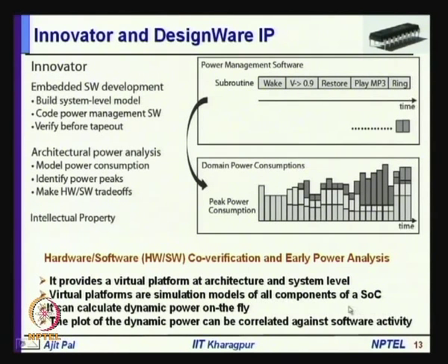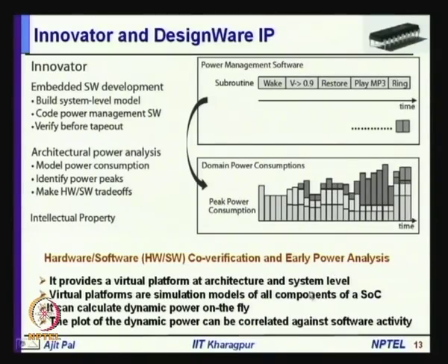models of all the components of the SoC as I mentioned, and then at the design phase it can calculate dynamic power on the fly. That means, you have got the simulation models, and using those simulated models you can run some application program, and as you run some application program, on the fly it can give you information about the dynamic power consumption, and based on that the plot of dynamic power can be correlated against software activity. So, these are the key features of